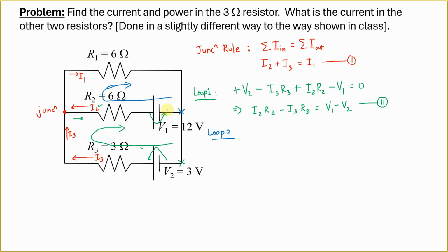And then again, I first meet the negative terminal of the battery, right? And then I have to go to the positive terminal. That means I am going against the field. Negative to positive is against the field. So again, I have an uphill battle to climb. So I'm going uphill, so that means my potential goes up, so I have a positive sign. So I have a positive V1.